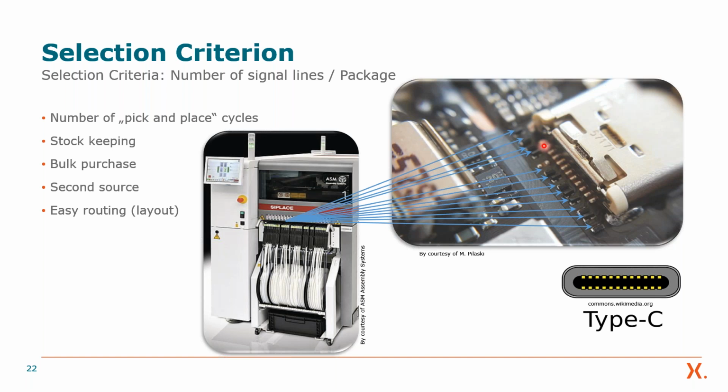Yeah, so it depends a bit on what you're looking at. For example, for standard automotive interfaces like CAN, probably a single device really makes sense because the matching is important, because the capacitance is rather high, because it's not that of a high-speed data link. But if you think of gigabit Ethernet, for example, this might also be an option.